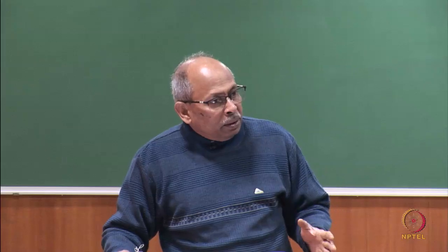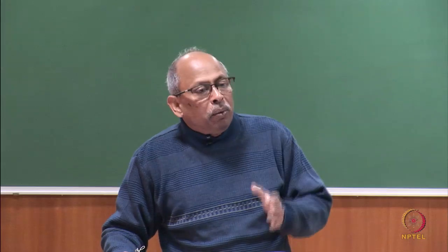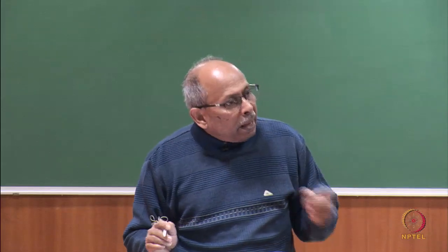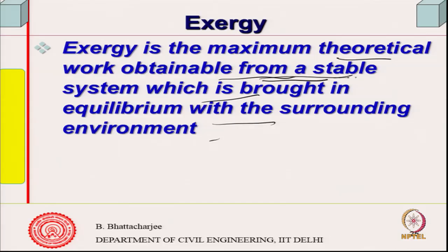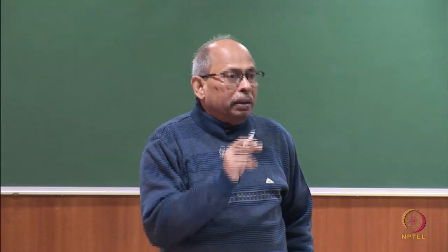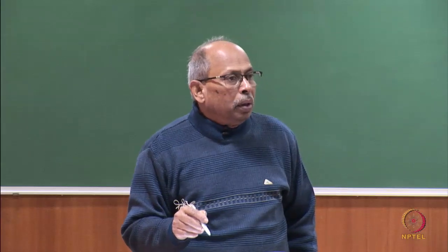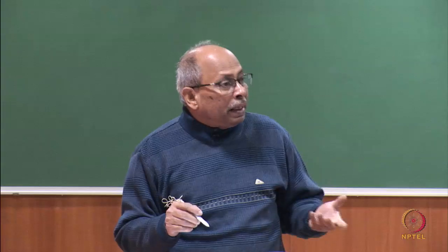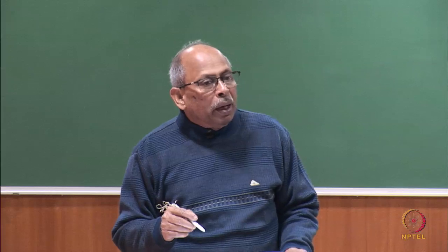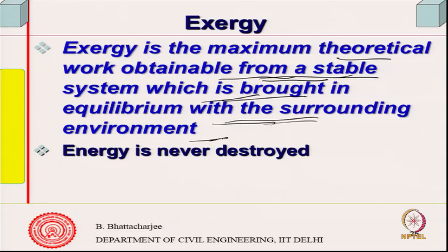This is the maximum theoretical work you can get. Energy is one issue, but whenever you are converting or using energy into work, there is a loss. This looks into the actual work that you are able to do, the theoretical work that is possible from a system which is brought to equilibrium with the surrounding environment. So, that is the work potential, that is what it looks into, and when one is trying to make the process efficient, let us say cement plants, for them it would be very useful. They should see how they improve the exergetic efficiency, as we call it, as opposed to energetic efficiency. We may not discuss this too much.